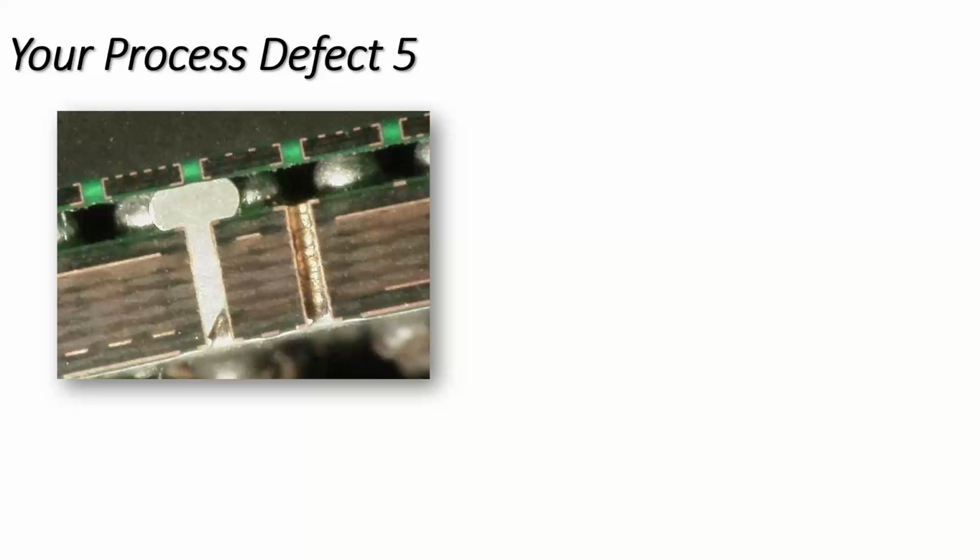But the wave solder machine they were using had a very aggressive chip nozzle. And by virtue of the design being possibly a little bit questionable, the process has allowed this to take place. So I think it's a good illustrator of what is bad practice.